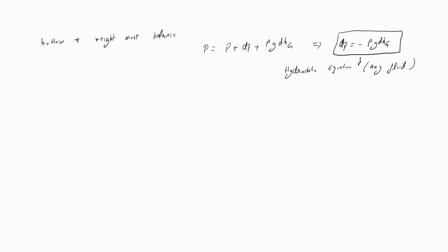So now if you notice here, this looks like a sort of a differential equation. Alright, it is a differential equation where dP and dHg are the differentials. So we can actually integrate this equation, to get the pressure. Alright, but the problem here is, here G is not constant. It becomes difficult to integrate this equation since it is a variable and it is depending upon the geometric altitude.